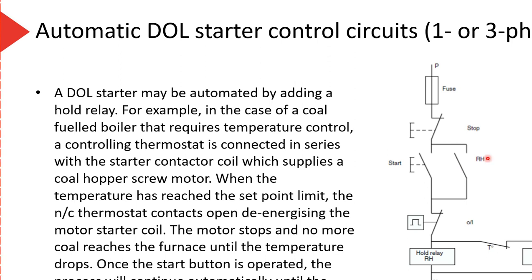So what have we got here? We have got another relay here. So power comes down here, goes through the stop switch. I push the start button and power goes through. There's a little overload there. That's just an overload, like a circuit breaker, right? So that's always closed unless something goes wrong. It's just sitting there allowing power to go through. Power goes through here, through the little temperature contact, through the contactor, and back to neutral.